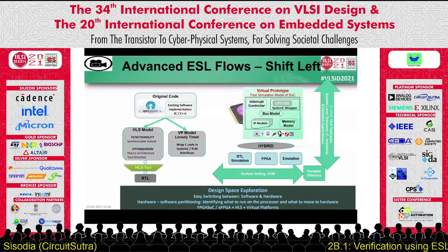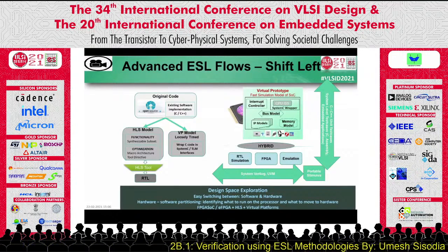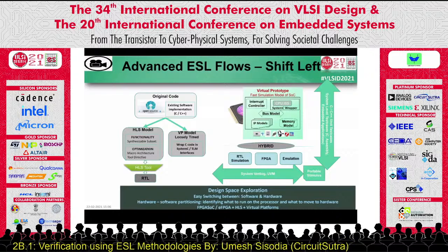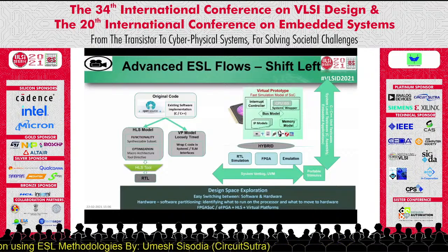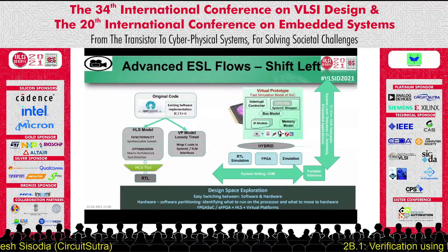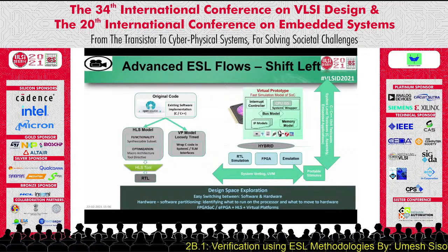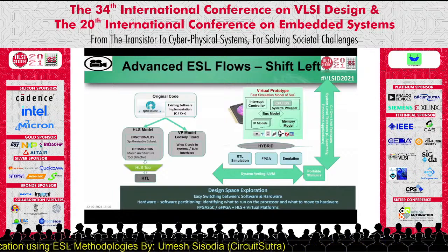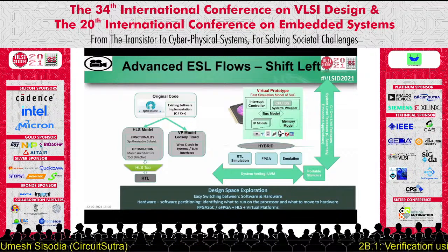These can be further used together with RTL simulation and FPGA simulation, thus a truly hybrid kind of environment, which enables a true continuum of verification that can flow seamlessly from the system level to the SoC level to the IP level. Moreover, these hybrid flows provide complete flexibility: in the entire cycle of an SoC, from concept to tape out, different teams can choose to use different techniques and different flows depending on their comfort level and on what portion of the design is available at that stage.